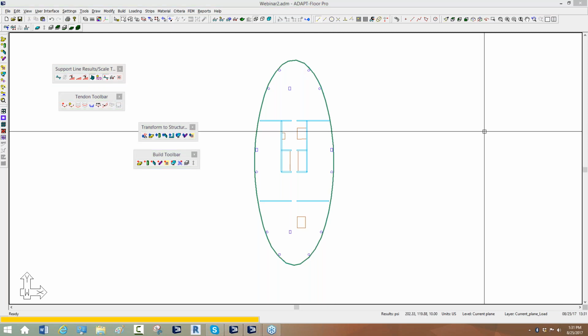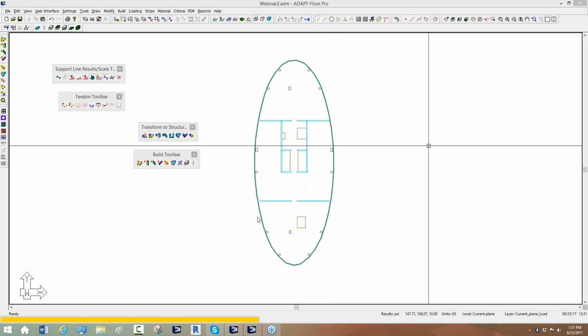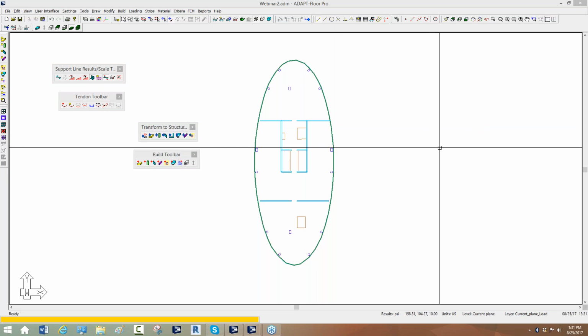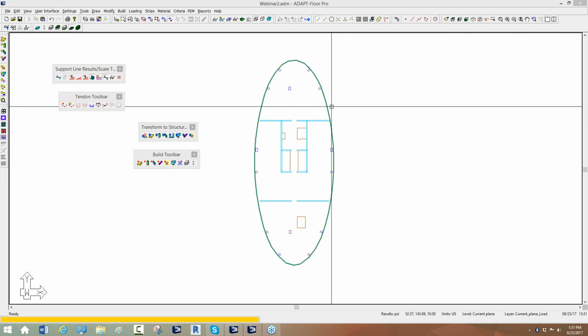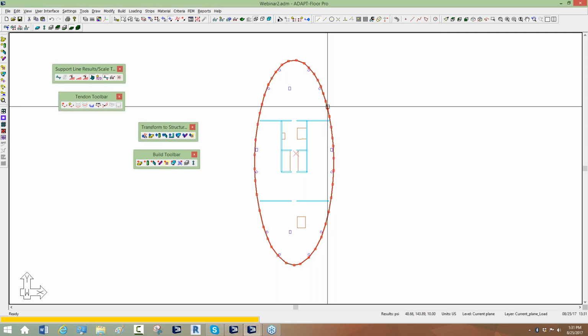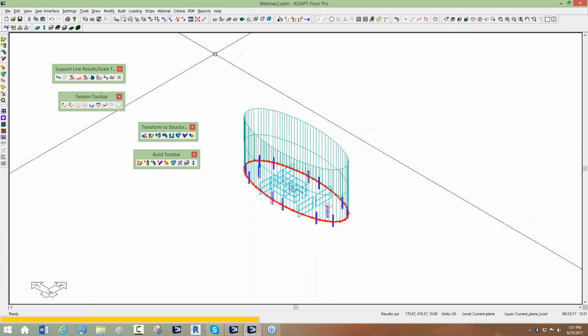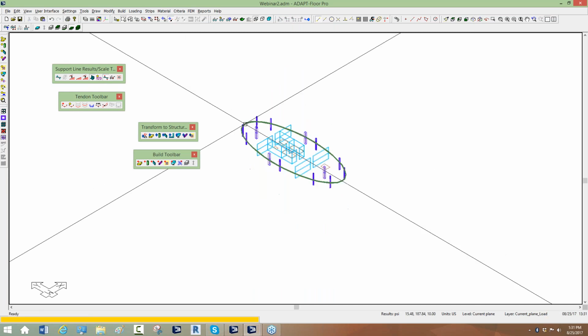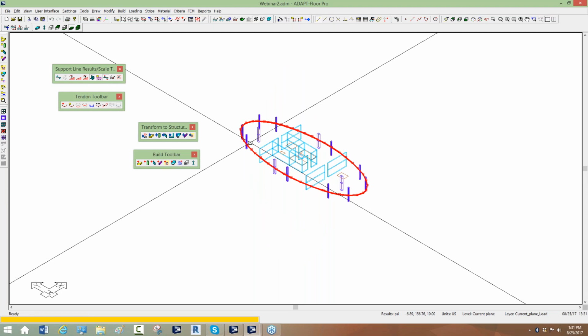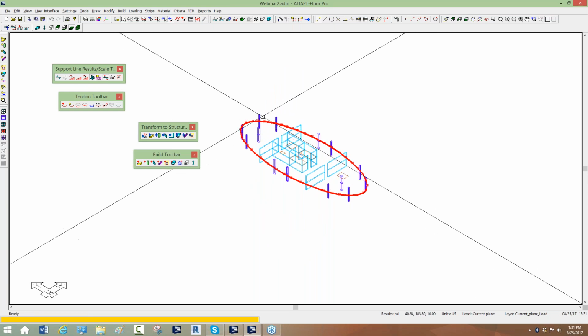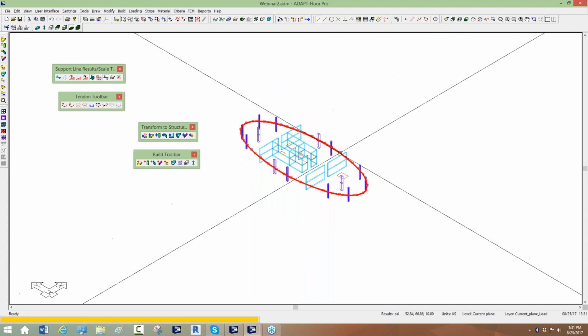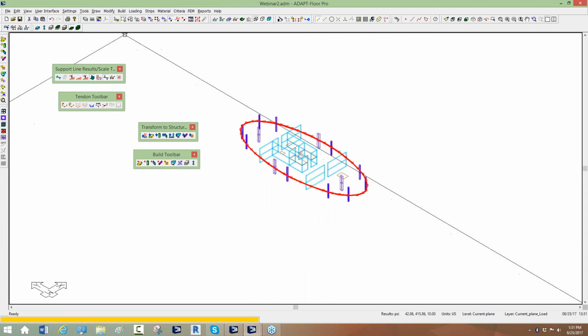There's one more question here. Let me go ahead and answer this. Yeah, can I add perimeter load for cladding? Yes, definitely. Let me do that. So perimeter loading is similar to patch loading, and then I can map it, or I can just use line loads. Line loads in this case would take a bit of time because I have to place in between each of these points, but mapping the load would be quite easy.